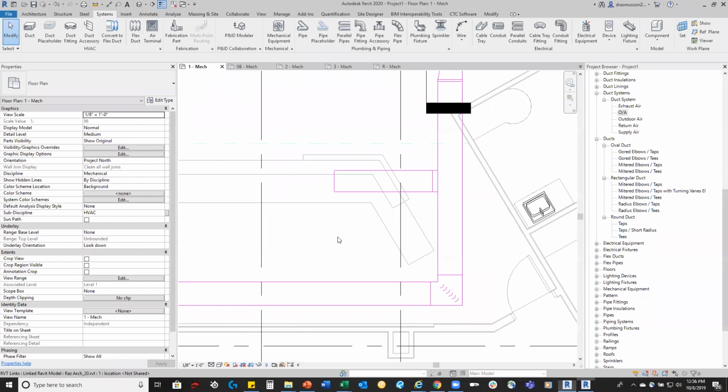Another thing that you can do in those situations, especially as it pertains to louvers and mechanical equipment, diffusers is another big one for this. Go in and edit the connector inside the family to be a universal connector rather than a specific system classification or system type, because that will allow that piece to take on the system properties of any system that's connected to it. For example, there's lots of grills out there from every manufacturer, be it Price or Titus, whoever makes it, right? That grill is just a grill. It can be used for exhaust. It can be used for return.